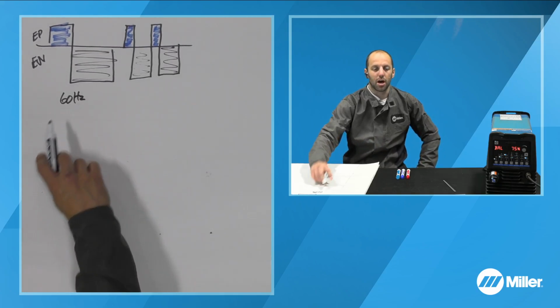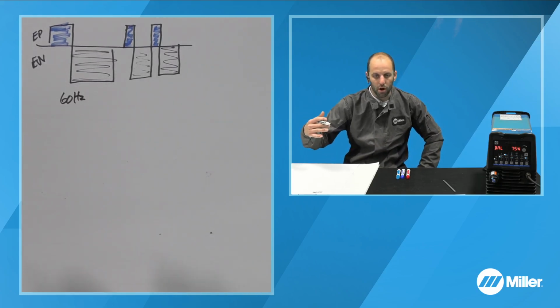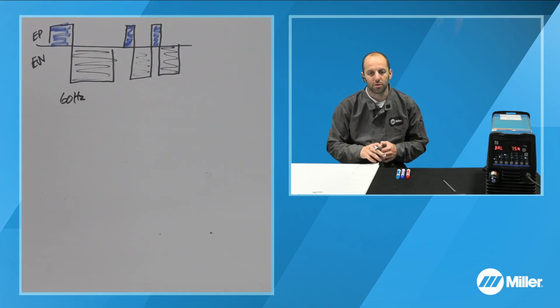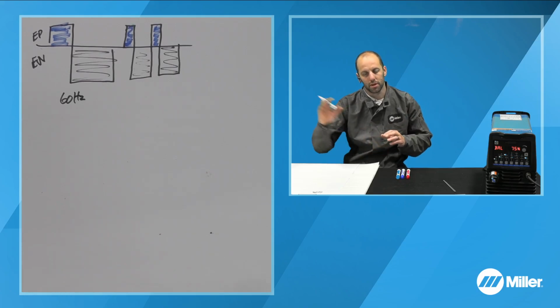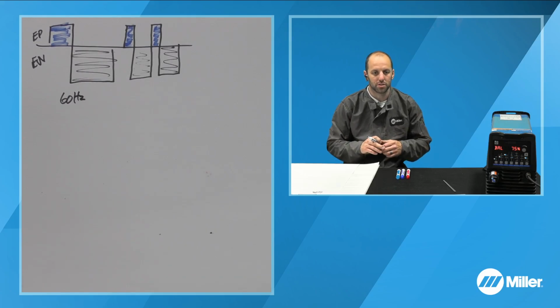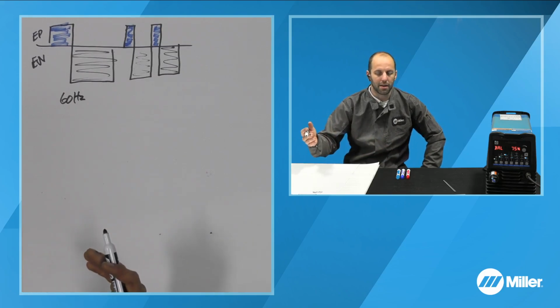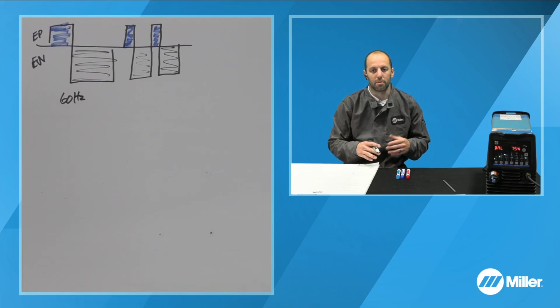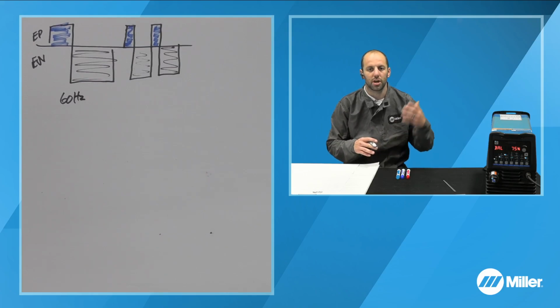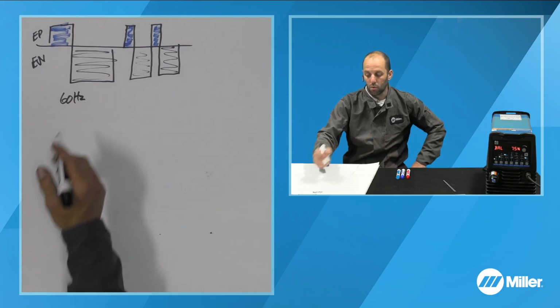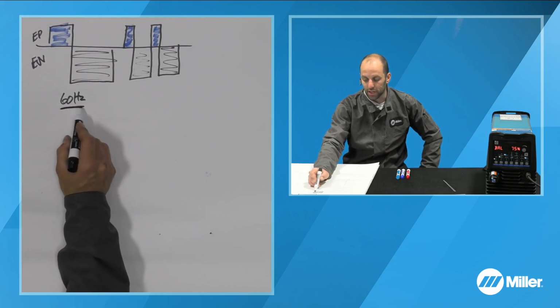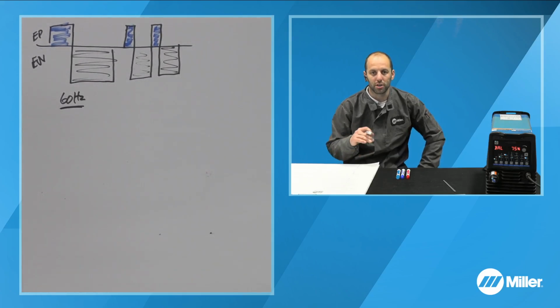When we have a 60 hertz output coming off the wall, it comes into the back of a transformer power source, and we're generating a magnetic field in that transformer. That field is collapsing when the AC input power changes directions, so it's expanding and collapsing magnetic fields. We're simply taking it from a high voltage, low amperage, and transforming it into a low voltage, high current setting on the output side of the welder. And so we're really tied and confined to that 60 hertz. Can't really do much with it.